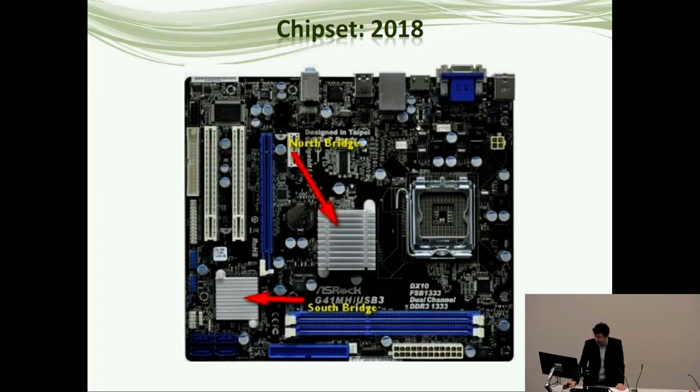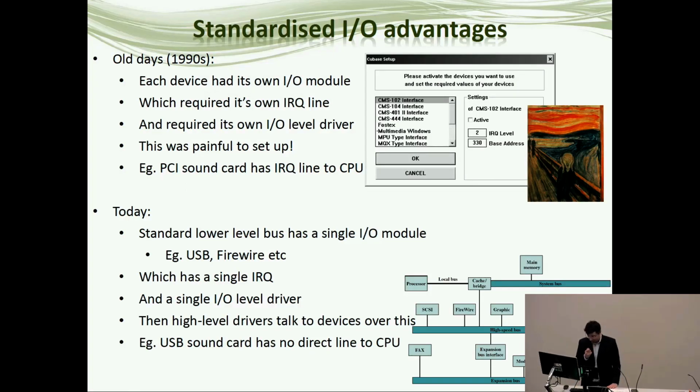So this is what things can look like in a typical, fairly modern machine. We find a big slot for the CPU, then we see the Northbridge with a bunch of cooling stuff on it. We see the Southbridge sitting down here, and we see the slots. These are, I think, PCIe slots, probably hanging off the Northbridge in this case, and PCI slots hanging off the Southbridge, where we're going to plug in our physical cards to put in our extensions.